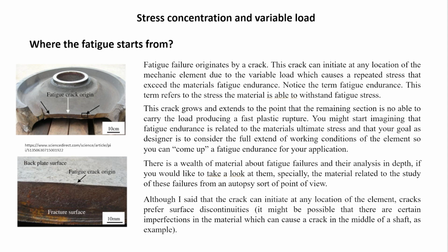And if you look at the material I posted about the exam applied last year, I believe one of them explains how the fatigue failure originated. And it's not something super complex to define. I believe this was one of the questions on the exam: can you explain how fatigue failure starts? Well, it starts because at some part of the material, most probably the surface, a micro crack initiates the whole process. That crack starts increasing because of the variable load, until it gets to the point that the remaining section of the part is so small that it cannot withstand the whole forces, and it breaks. And that was the whole answer to that question.